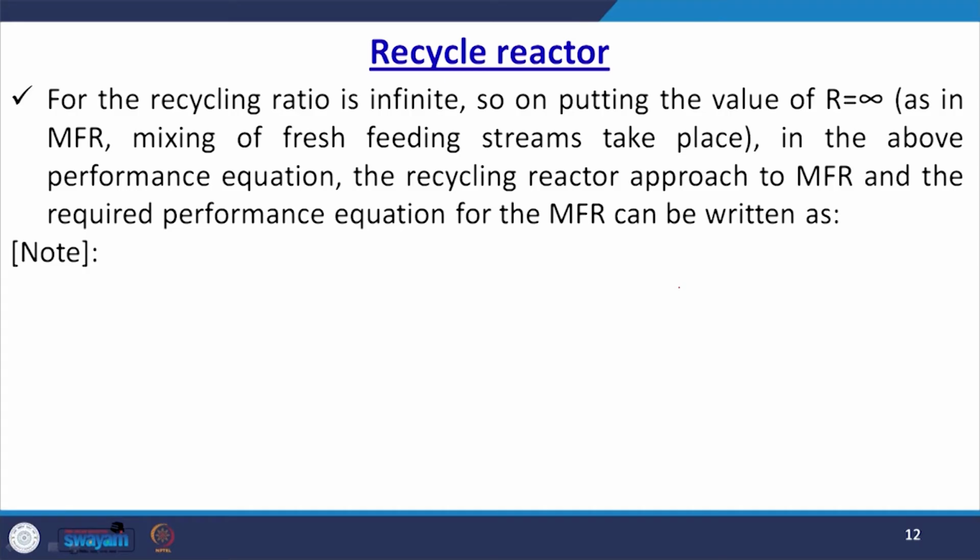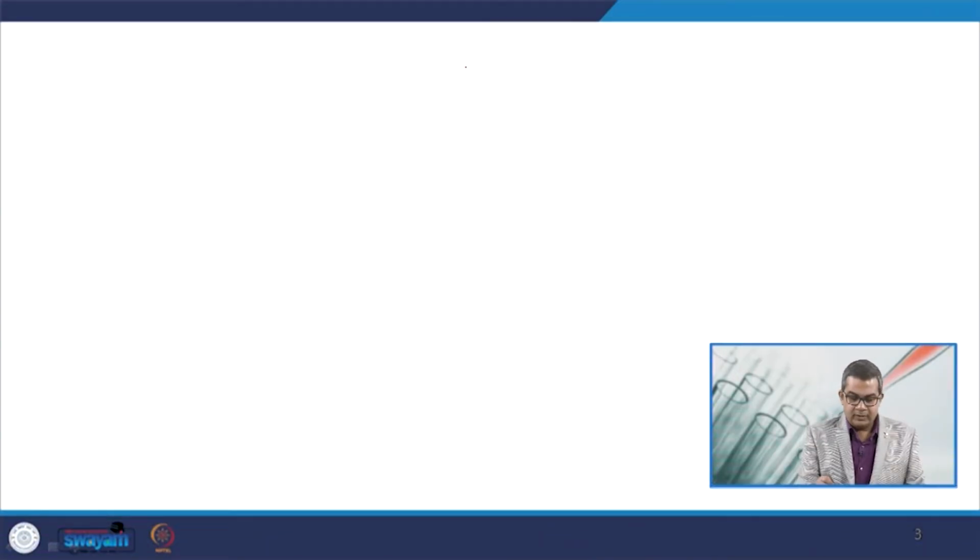Now, if we talk about the recycle ratio being infinite, on putting the value of R tends to infinity, sometimes we use this particular condition in a mixed flow reactor, so mixing of the fresh feed may take place. In that case, the performance equation for the recycling reactor approaching a mixed flow reactor can be modified like this when R is equal to infinity.